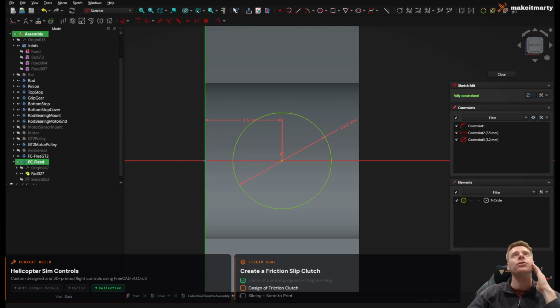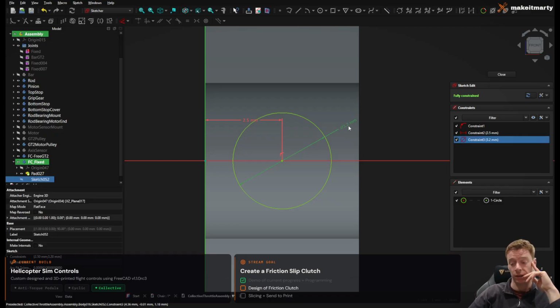Pilot hole. So for an M3 non-flanged with an outer diameter of 4.4 mil, the pilot hole should be 4 mil. For an M3.5 at 5.2 mil, the pilot hole should be 4.8. For an M4, 6.1, 5.6. So it's going to be like 0.3, 0.4. Okay, so we want the pilot hole to be slightly smaller, apparently. So let's make this 3.